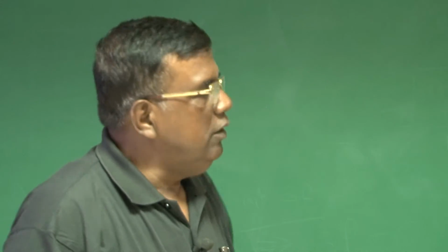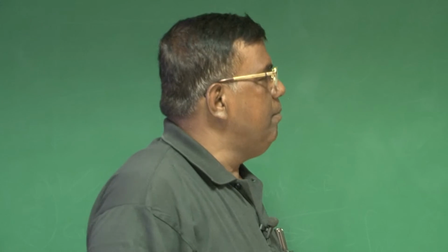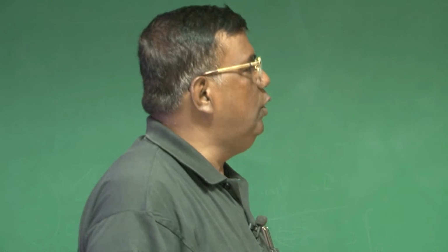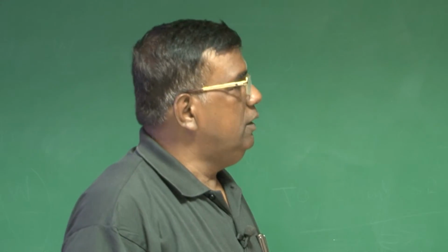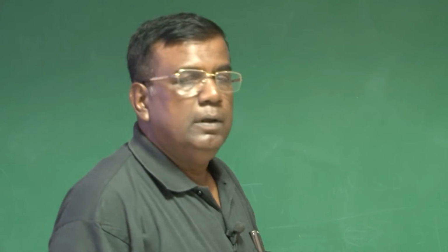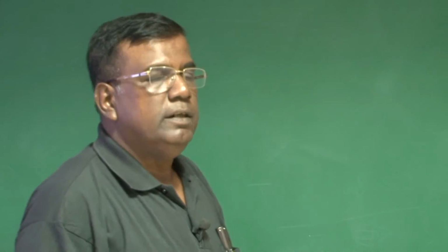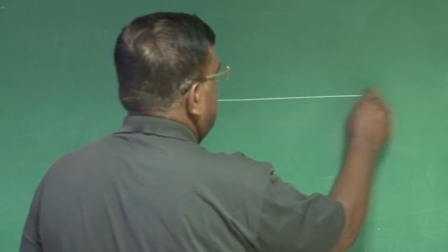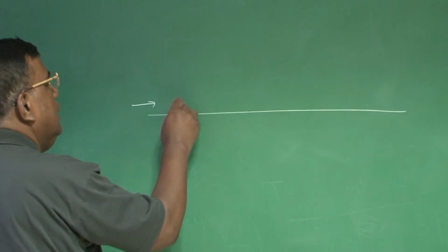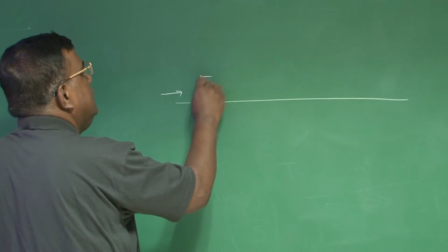I thought I must also add something on balance field length. You know what the balance field length is. The requirement is very simple. If I have a multi-engine airplane, let's say 2 engines, and it starts taking off from here, and let's say close by, one engine fails.